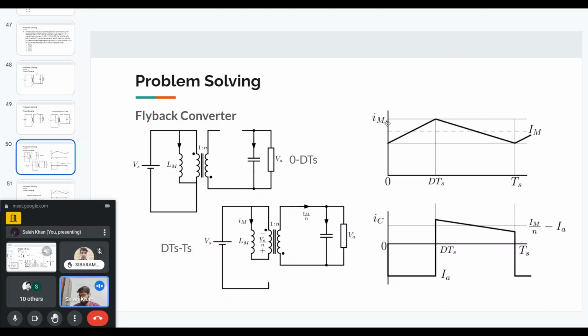The reset circuit depends on the converter and how it functions. The flyback converter is different from other transformer-based or isolated converters in that the transformer basically stores energy. That is why it is not strictly a transformer, because a transformer, by definition, will not store energy. It will directly transfer energy.